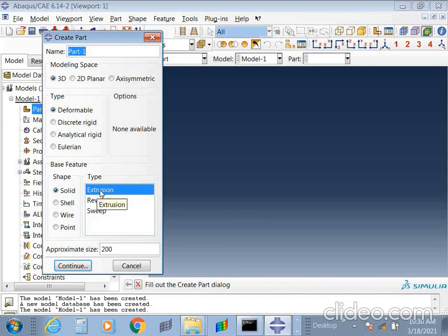Like you want to revolve the sketch, or you want to extrude it, or you want to sweep it. Three options. Extrude in the sense your model or geometry sketch will be having certain thickness over it, and revolve in the sense at a particular axis your geometry will be made into a revolution. And sweep, again what layer of sweeping, you understood? So that methodology will be used.